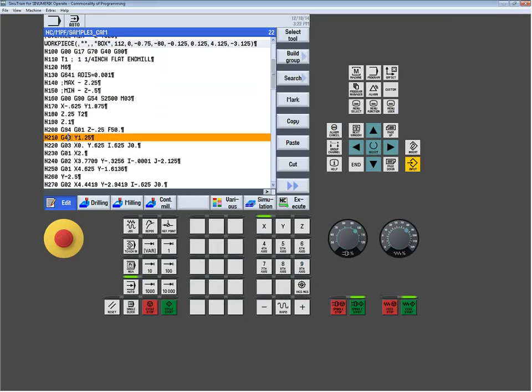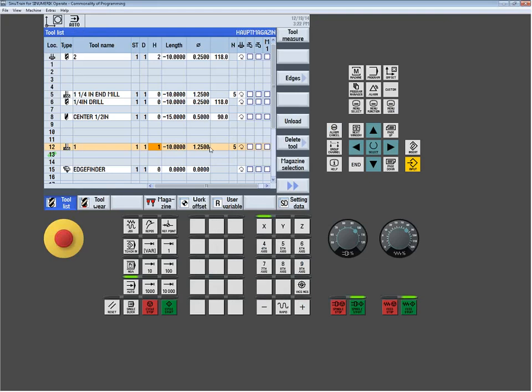absolutely. The only thing you've got to be careful of when you start to use cutter comp is if the CAM system's taking into account the diameter of the cutter, and then you've got a G41 and you're putting the full tool diameter here, it'll double comp it. So you've got a couple options. If you zero out the cutter comp here, you're not going to be able to get the full solid modeling to work properly because we'd have no diameter of the cutter, so the graphics will look a little funny.